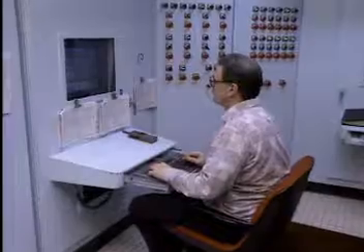When a heat exchanger is in operation, operators must routinely check the unit to ensure that it's operating properly. This may include checking temperature and pressure instruments to make sure that their readings are within normal operating ranges, as well as checking the condition of the heat exchanger itself.